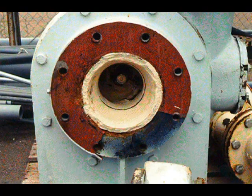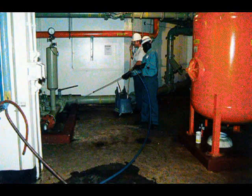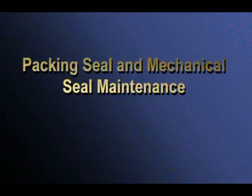Cleaning and corrosion control are other important aspects of any maintenance program. Because the life of a lubricant is greatly affected by the amount of dirt, dust, scale, and moisture that get into it, a regular cleaning program should be put into effect. This cleaning program should include the cleaning of all areas with high-pressure air or water without damaging motors and other equipment or injuring personnel. Additionally, the program should include the cleaning of floors, removal of rust on metal surfaces, and repainting of all surfaces. Major centrifugal pump maintenance items are the packing seal and the mechanical seal.